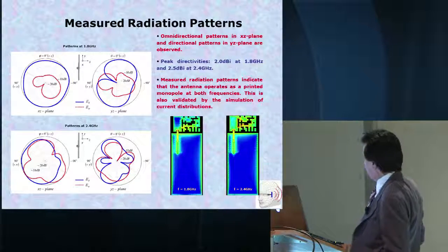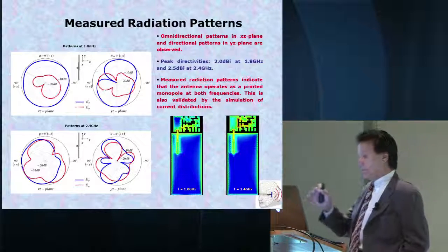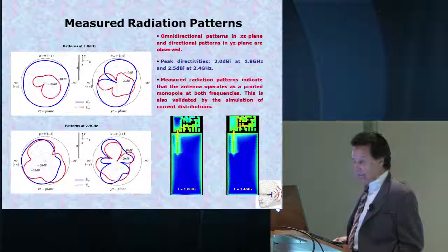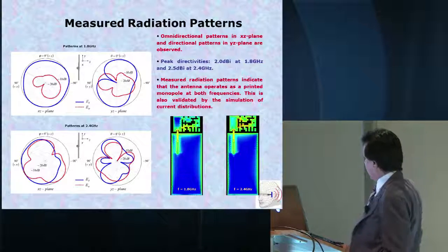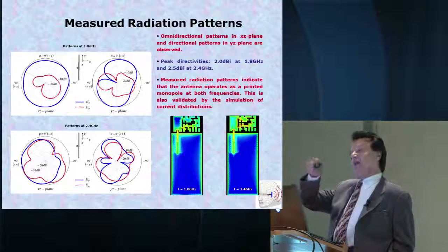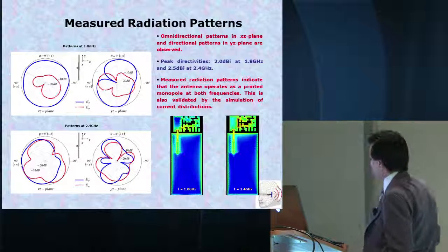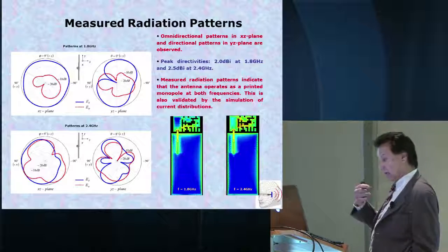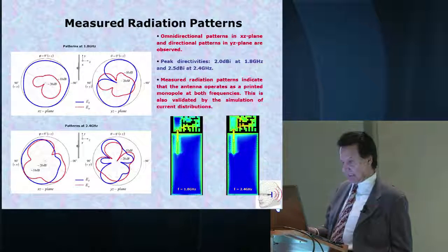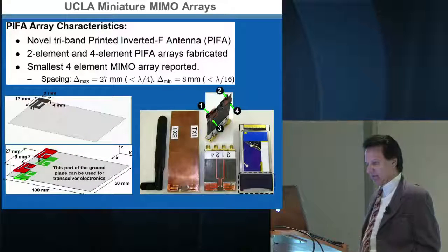So this is 1.8 and 2.4 gigahertz. So we wanted to see what pieces of these antennas are doing most of the radiation at different frequencies, and indeed you can now go and look deeply. And that brings me to the other ring of the Olympic, visualization. Because electromagnetic visualization would allow us to understand now the physics of operation of some of these very different class of antennas.